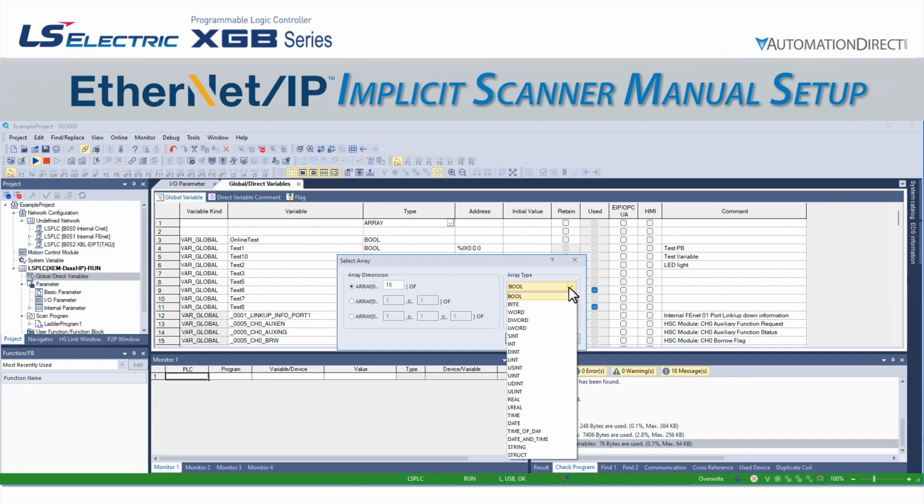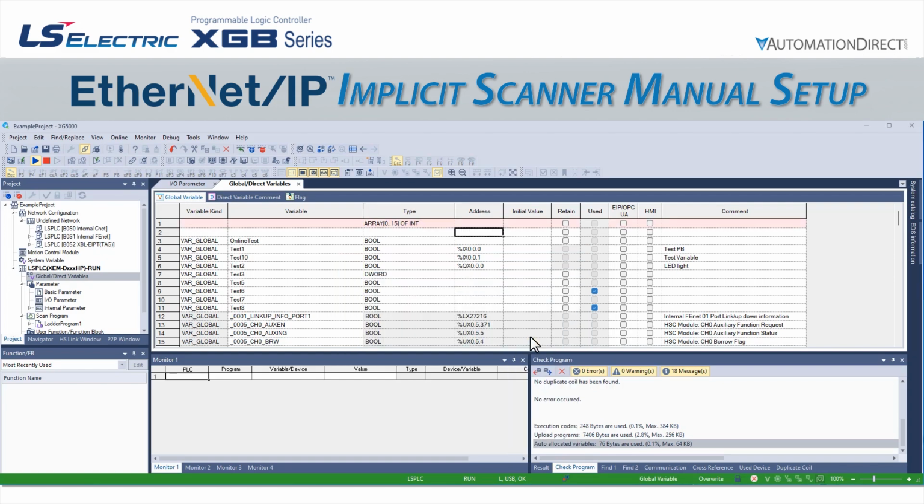For 16-bit data size, the array type can be either word or int. If we use word, it will display the value in hex by default, so let's use int to see it in decimal. We click OK, and we will name this array EIP_input_array, and make it a global variable. It is also important to make sure we check the box for EIP OPC UA. This allows the PLC to use this array as part of our EIP transfer of information.